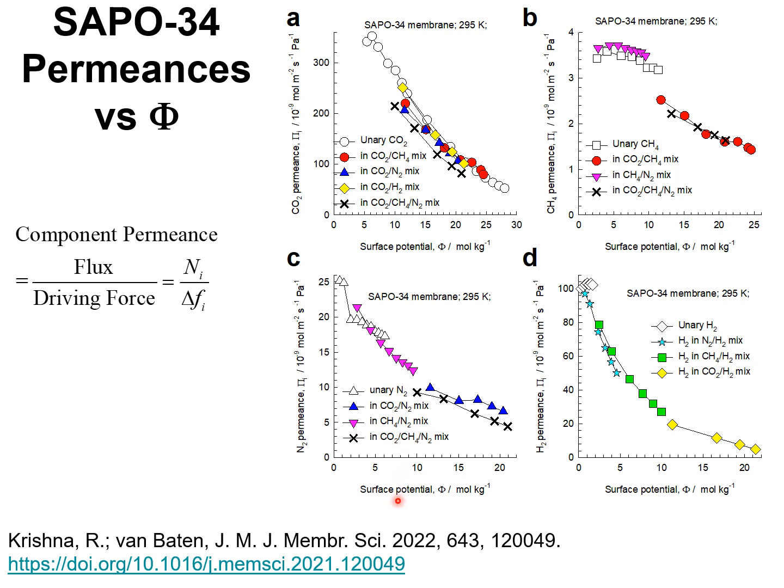The important point, of course, is to make the comparisons not on the basis of the partial pressures at the upstream face of the membrane, but at the same surface potential at conditions corresponding to the upstream compartment in membrane permeation studies.